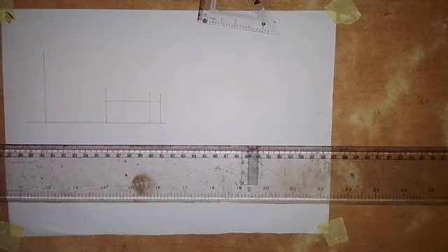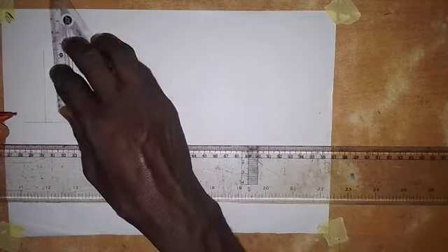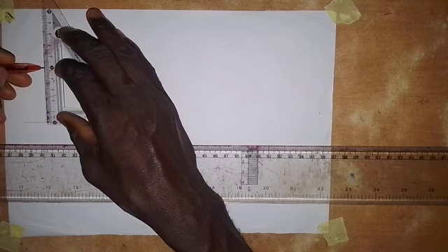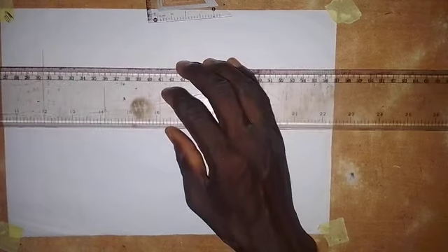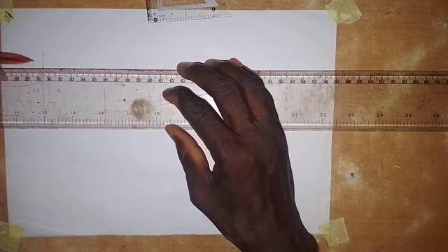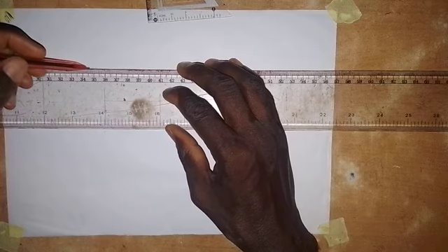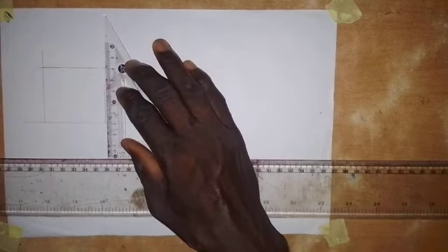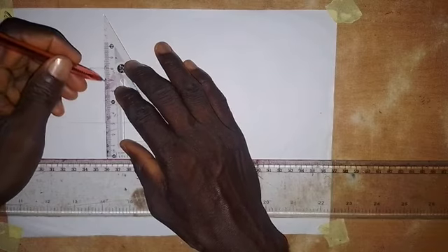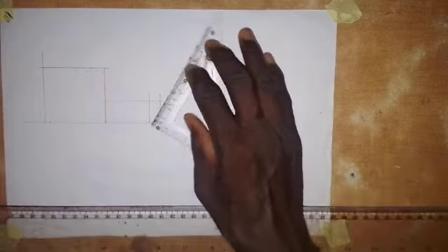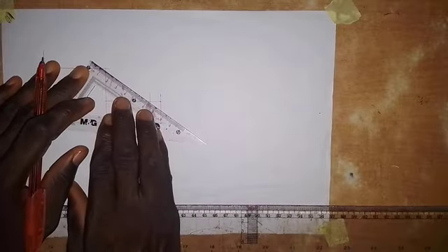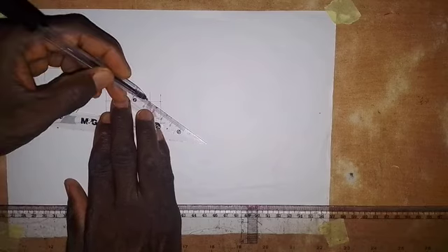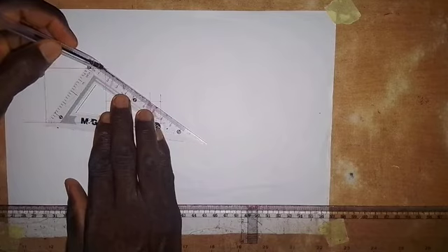Okay, now for the end here, where we have the height of that end part to be 50 millimeters, I will draw a horizontal line here. So I've taken a measurement of 50, so I will draw a horizontal line forward. Okay, so at this point I'm going to connect this together like this. Okay, connect this together. So the elevation of the web, which is a triangle, we just join this point together. So I'll make it a thick line at once, making it a thick line at once like this.